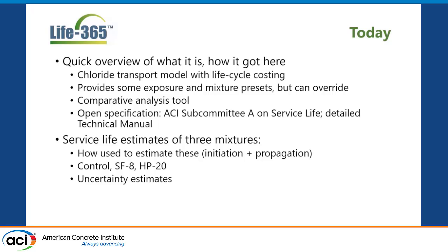Open specification that I mentioned, the technical manual itself is extremely transparent. It talks about all the lab tests. It talks about the chloride mechanism that's modeled in 2D and one-dimensional finite differencing, and is documented as much as possible. If somebody wanted to write another piece of software that does the Life-365 approach, there's enough information in there for you to be able to do that. It's a lot of work, trust me, but you could.